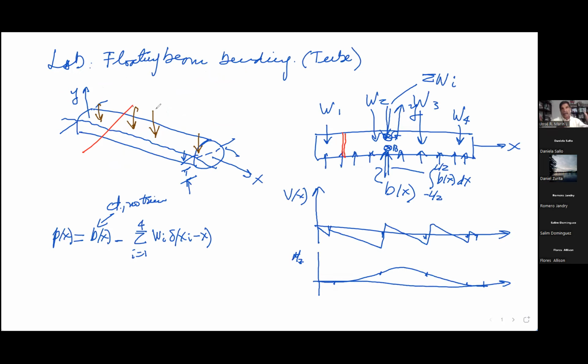So we make a cut at different points. On those points, to have equilibrium, we have shear force and bending moment. This is what we call the section method. In this case, we install this load cell, and supposedly it should give us the shear force.